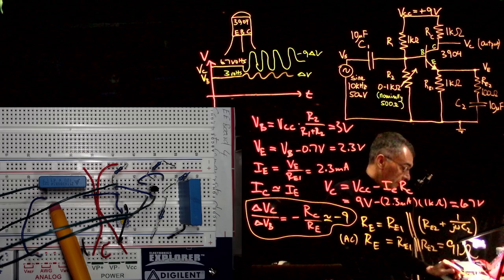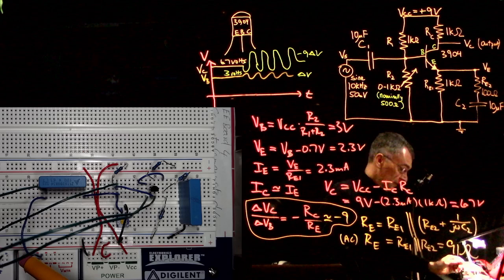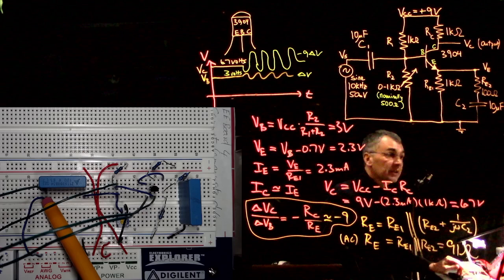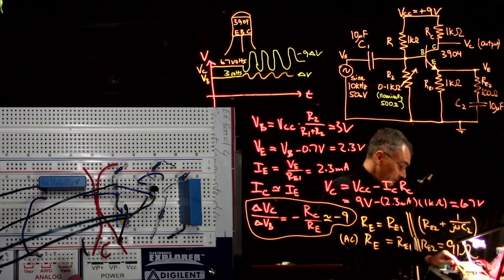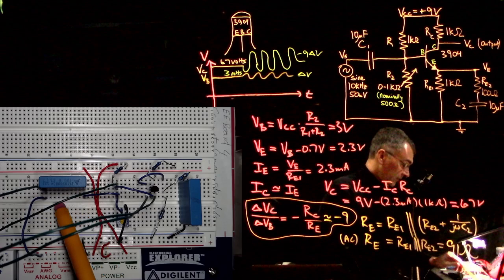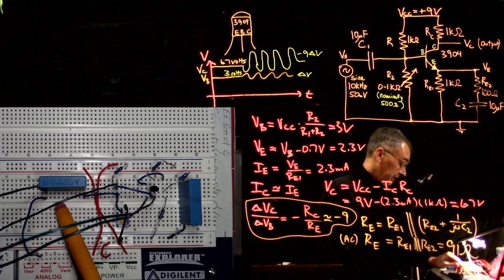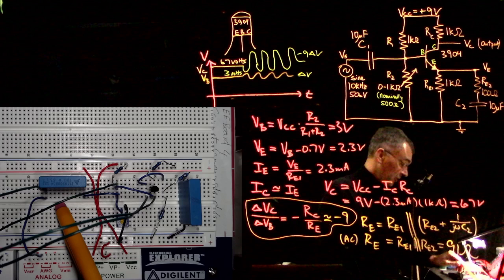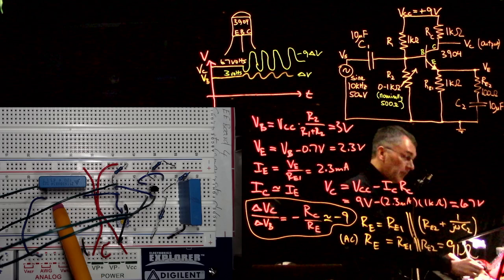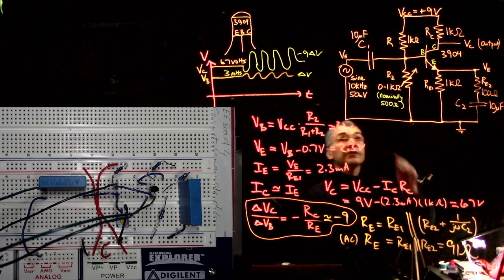So I made waveform channel 1 come in over here on the left. And then this big capacitor is C1. It's kind of hard to work with these 10 microfarad capacitors, so you kind of have to design everything else around where you put them, it seems. And I made oscilloscope channel 1 monitor the input signal, which is on the left side of C1.